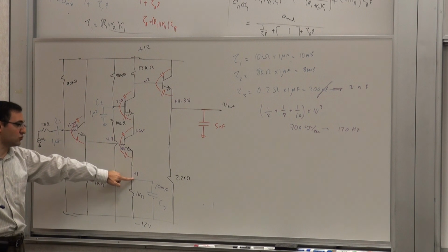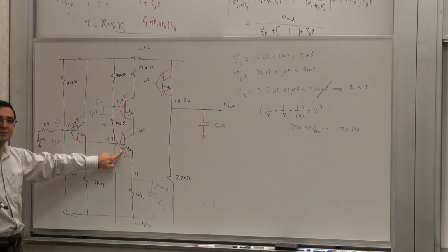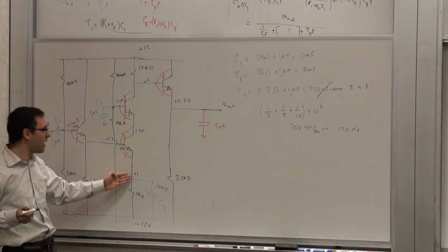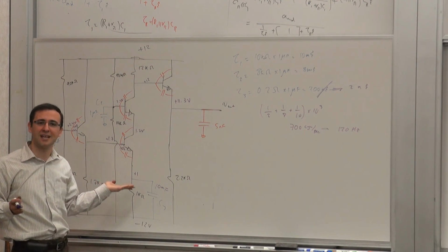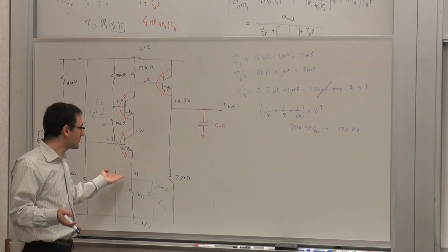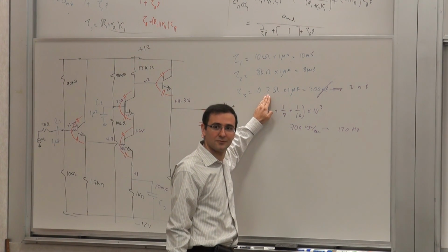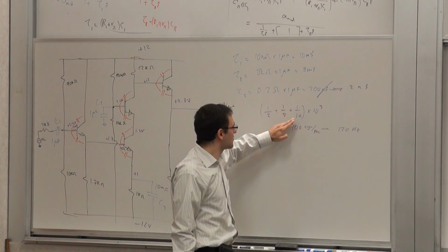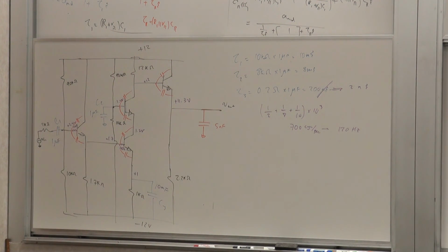So this resistance cannot drop below a certain minimum. So 30 ohms in series with 1 kilo ohm is still 1 kilo ohm, divided by beta, it's going to be 10 ohms. So it can't really go below 10 ohms, because it's the RB of the transistor itself. So if it were 10 ohms as opposed to 0.2 ohms, then this would be like 50 times larger. So this really didn't need to be this big in practice, if I had taken that into account. But anyway, so that you get the idea.